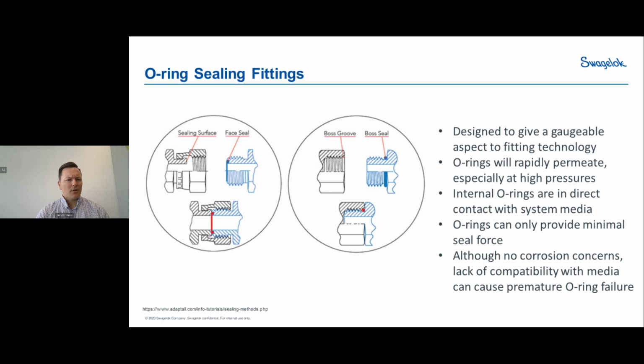And the same would go for a lot of gasket style fittings as well. This allows the user to really identify that this connection is made up correctly or fully, and it's not reliant on just increasing the forces between the two tapered threads.